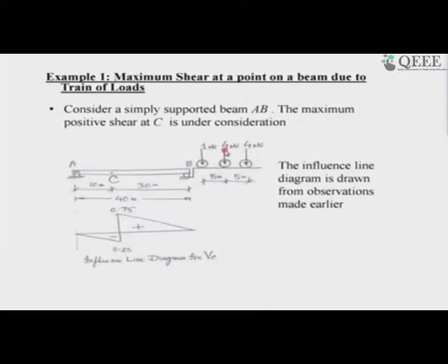If I have multiple loads, carefully examine the influence line diagram for the shear force at C. It has a linear segment, it is monotonically, you can say, decreasing in magnitude, goes to more minus as you move from left to right, and this actually monotonically and in a straight line is decreasing in magnitude, positive magnitude.